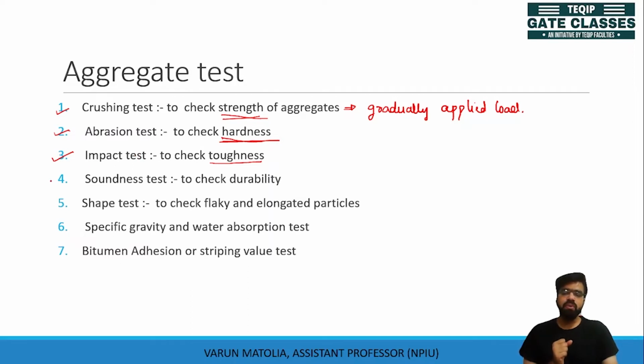Then we have soundness test. Soundness means how does aggregate behave in different weather. At different weathering conditions, if aggregate behaves properly, this is durable. If it does not behave as desirable, then it is non-durable. So we check the durability of the aggregate through soundness test.